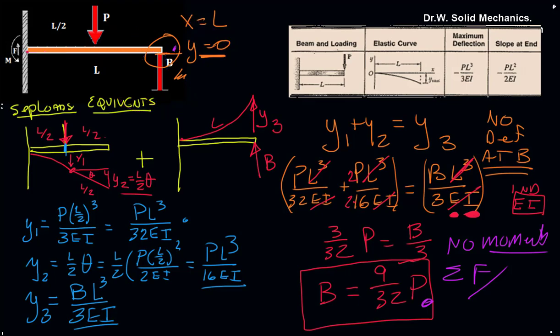We're able to go directly from this load configuration to our equivalent loads, to our equations, and then solve for the force at B without ever going in and doing any other moment or force equations, which is truly remarkable. Once we know this, that beam becomes determinate and we could finish it and find moments and the force at the wall after that. So an extremely useful benefit of these elastic curves.